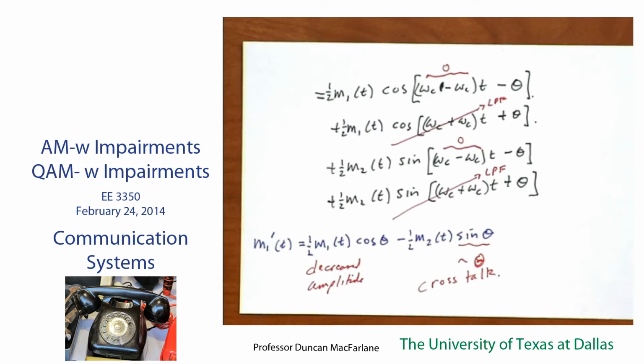Now think about it. If theta of t is varying, that's not too different from saying that my frequency is shifting. The math will work out about the same. In fact, I encourage you to do that tonight: do the impairment where I have an omega prime going on. As this wiggles around, this signal will go down, and the amount of crosstalk will come up.